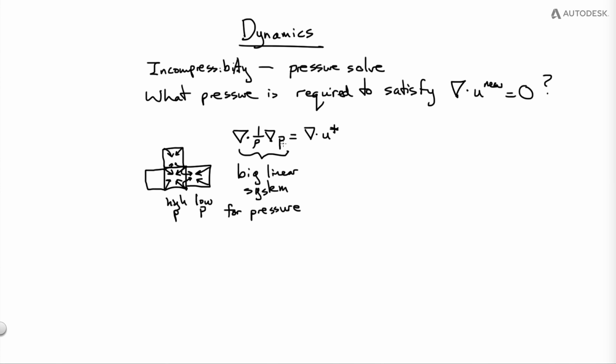It turns out we don't actually care if this is absolutely exact. The other errors that are made in the solver may actually be larger, and as long as we balance the errors so one isn't obviously causing a visual problem, it's fine. So what we use is something called multigrid, which actually works very beautifully with our multi-resolution tile tree.